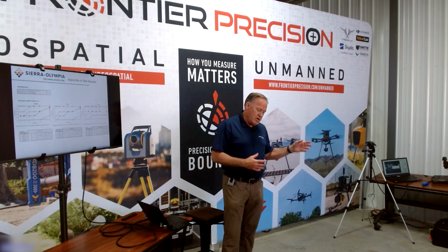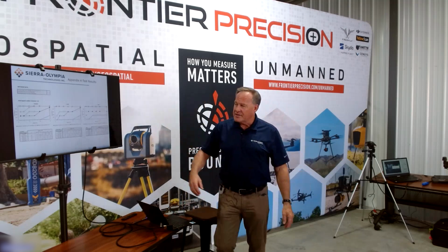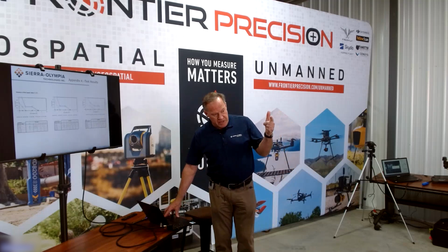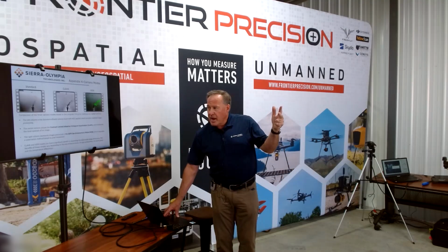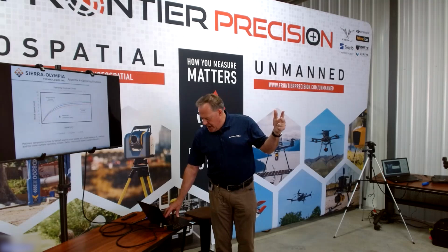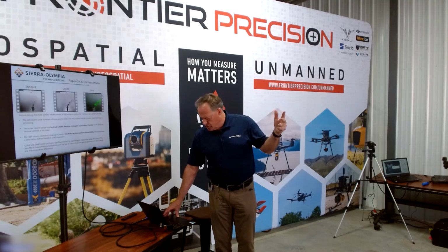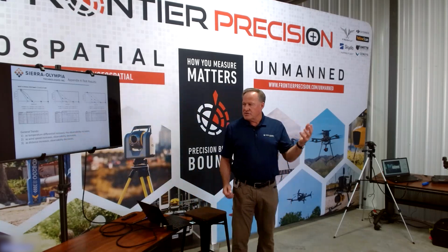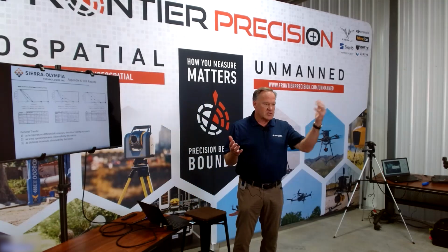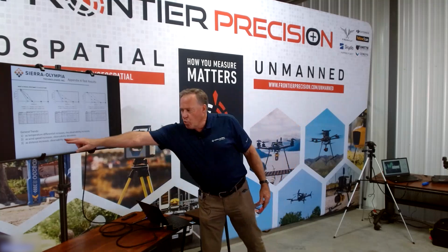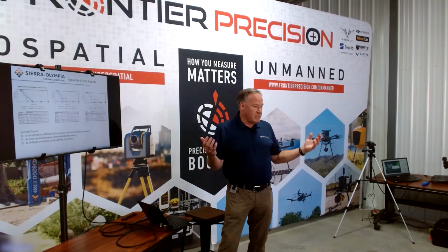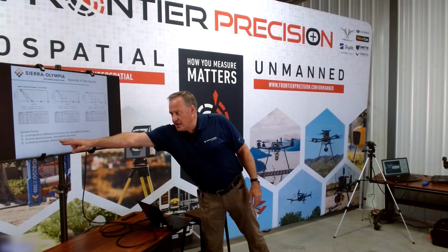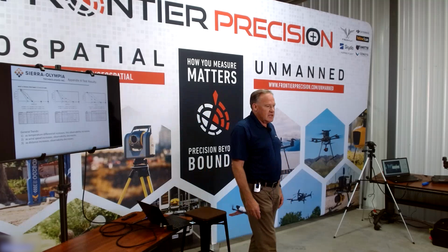And then what we did is we created hundreds of graphs and plots about changing the distance, the wind speed, and the delta T. And the end result of that came out exactly kind of what we thought it was going to be. The general trends that we found, as the temperature differential increases, the observability increases, just what I said earlier, right? As wind speed increases, the observability decreases because it disperses the gas, right? And as distance increases, observability decreases.